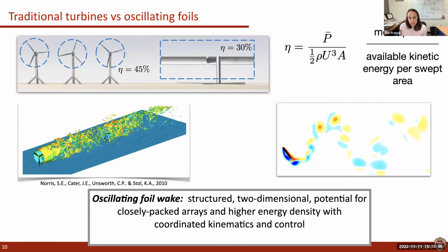If you rescaled it by, say, the chord length of the turbine, you would get a different metric. Instead of an efficiency, you would get a non-dimensional power, and that would be a different metric to compare against. So it just depends which definition you are trying to optimize.